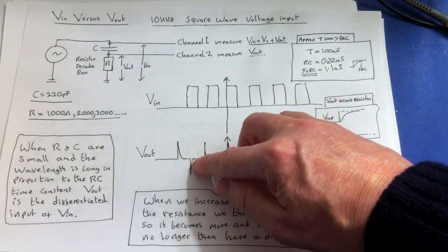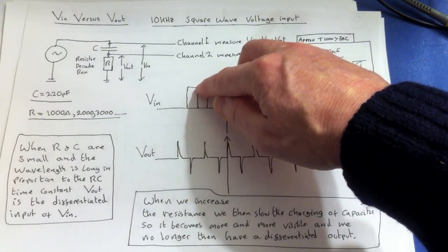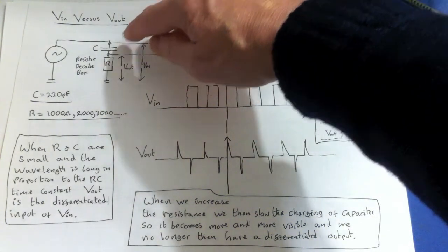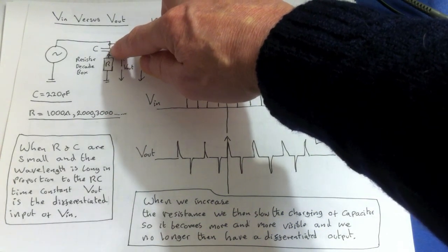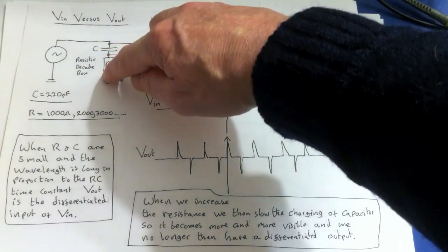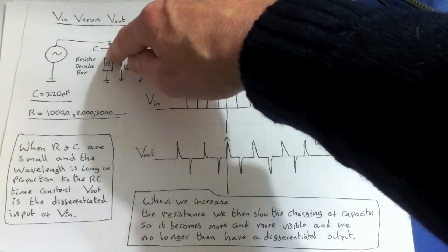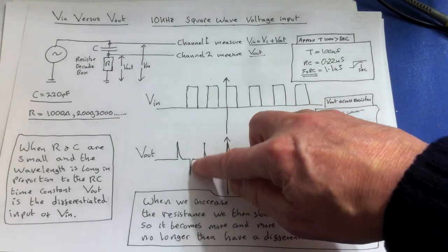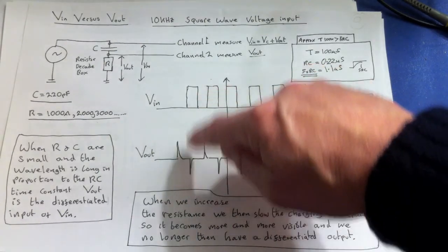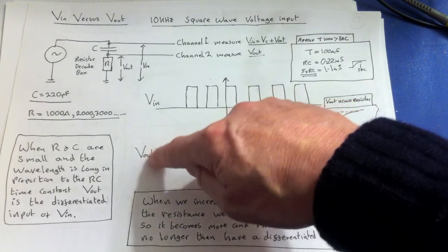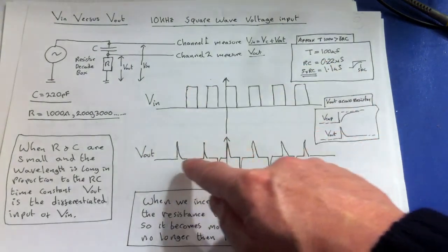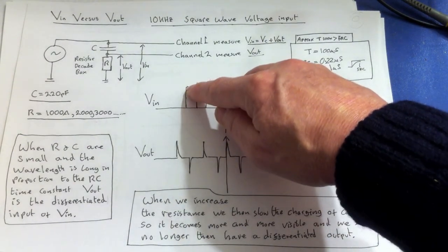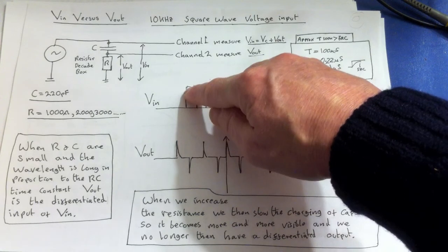Well, you get a spike in the opposite direction then, because obviously the capacitor is discharging then, and the voltage at that point, you're getting a negative voltage coming back out, and so obviously you get this minus as the voltage is coming back out, back into V in. You're going to get this minus spike here, so hence you get the minus spikes. So that's really why you're getting this correspondence between V out and V in. And what it's effectively doing is it's showing you this gradient here, which is why we call it a differentiator, because it's showing this gradient.